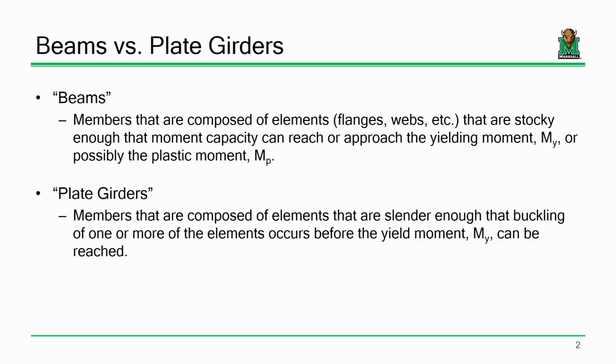If you've taken a course in steel design, you probably remember that whole concept of lateral torsional buckling, the idea that you place a load on a beam, part of the beam is seeing compression, the other part's experiencing tension. From mechanics, you all know that things in compression like to do this thing called buckling. Well, part of the beam wants to buckle, part of the beam doesn't. There's this internal conflict of stress, and this is resolved by the beam kicking out and twisting, right? If we're looking at a beam, the whole beam would want to kick out and twist. Plate girder, not so much.